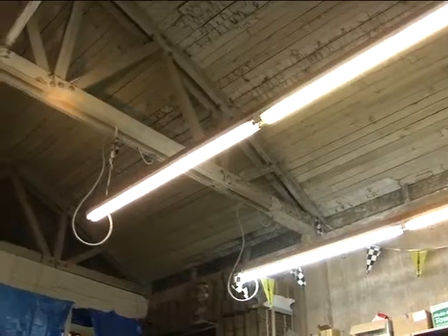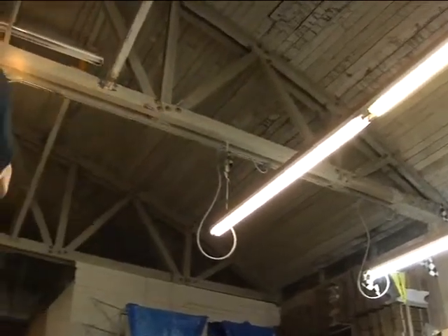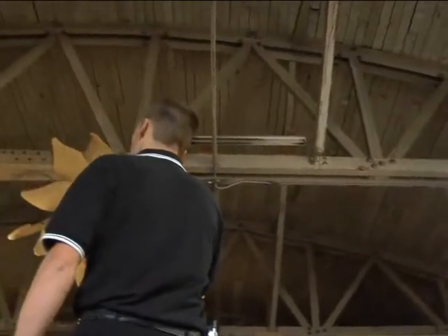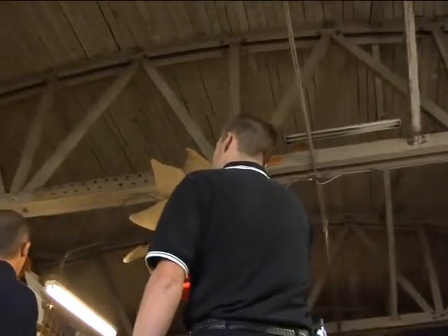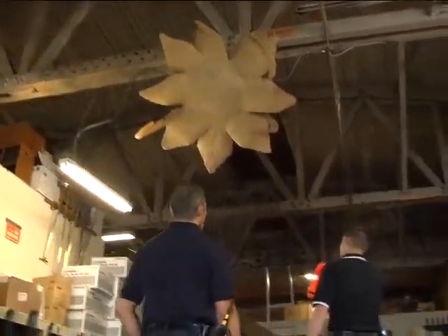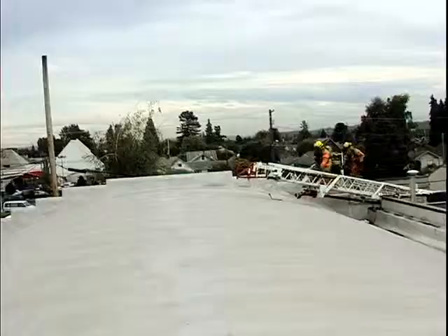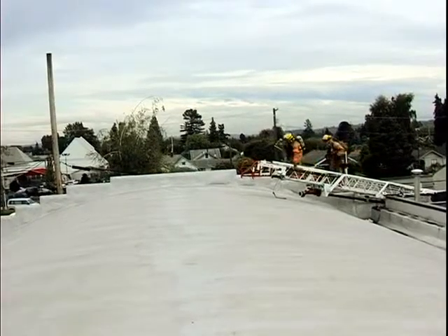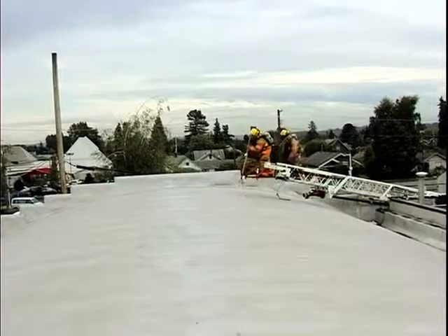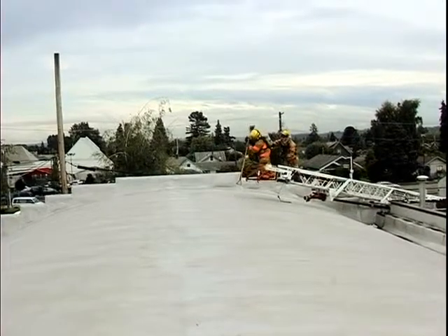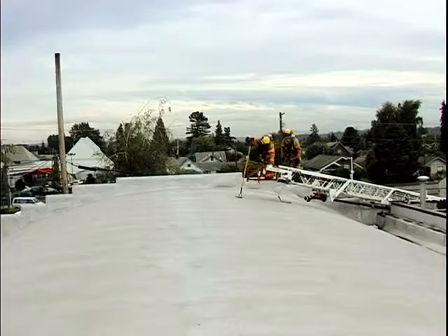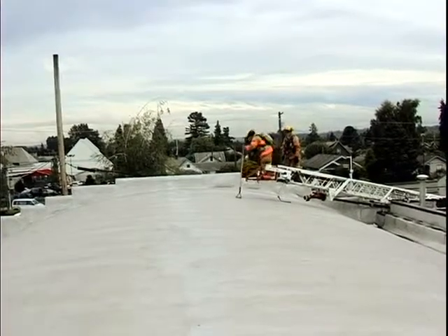An additional hazard for arched roofs is that they are usually supported by bowstring trusses. These trusses have large spans of space between them, and when weakened, large sections of the roof may collapse without warning. Because of this danger and the difficulty of standing on these curved roofs, firefighters should ventilate an arched roof only from the safety of an elevated platform or aerial ladder extended to the roof.